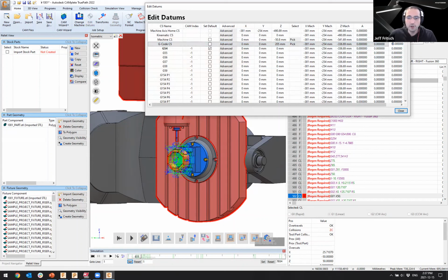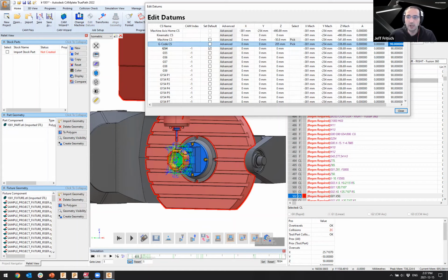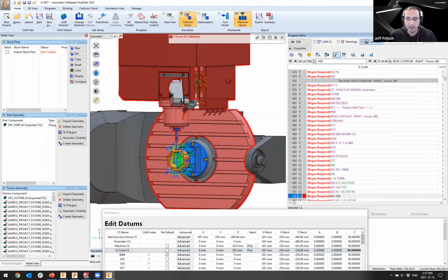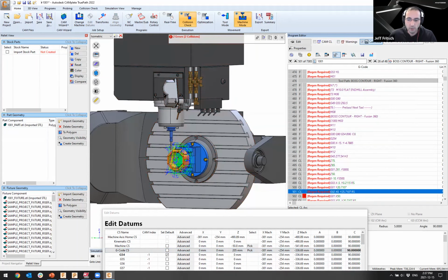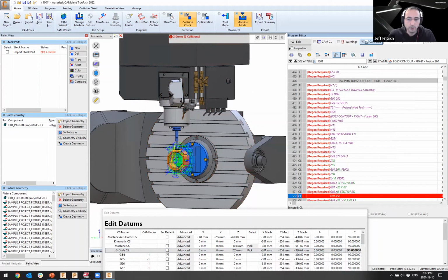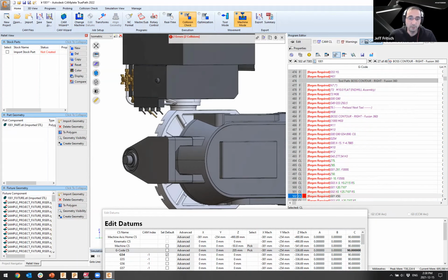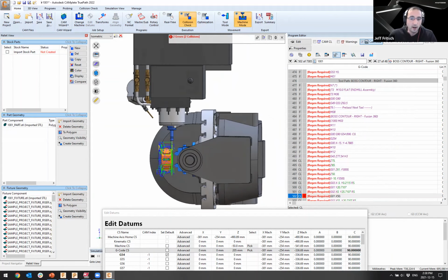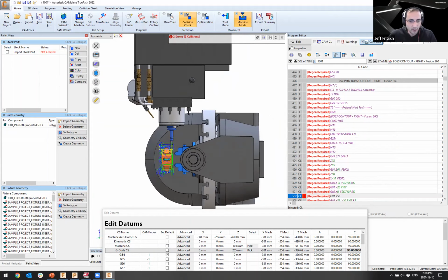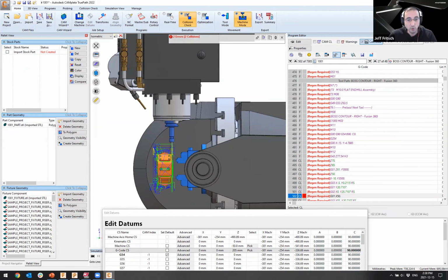But for argument's sake, the question would have been, what would happen if we just rotated this whole thing 90 degrees? Literally, when we go to clamp it, we just rotate the whole thing 90 degrees. At that point, it would have become super clear that we didn't necessarily need to look at the tooling or the fixturing. The fixturing definitely helps in any situation, but at that point the tooling could have stayed a little bit shorter and a little bit more rigid.